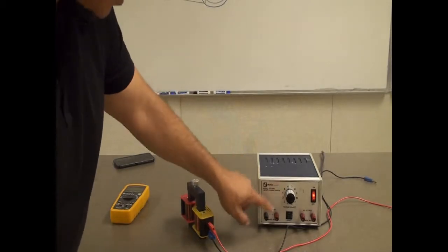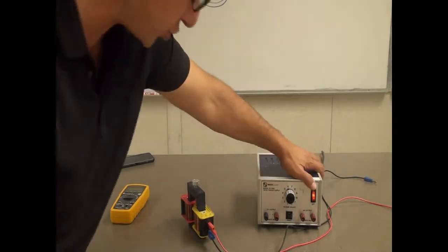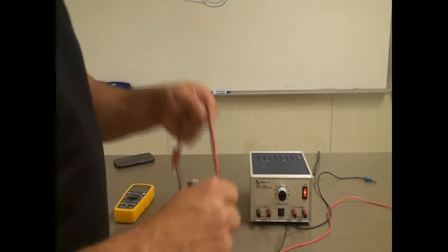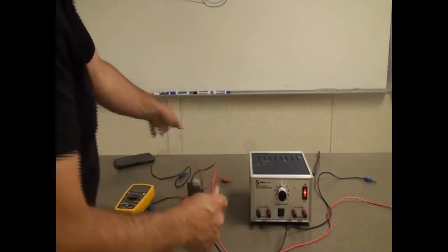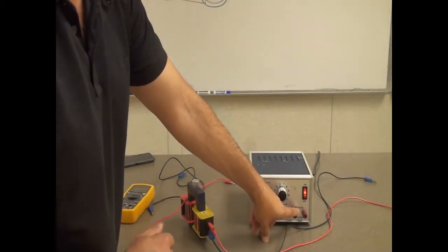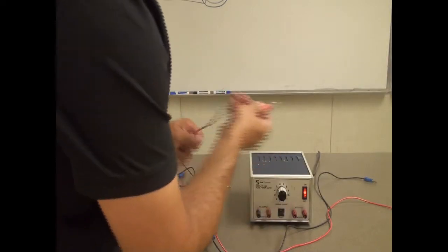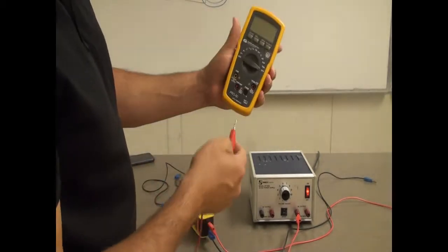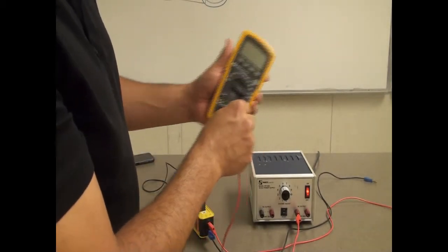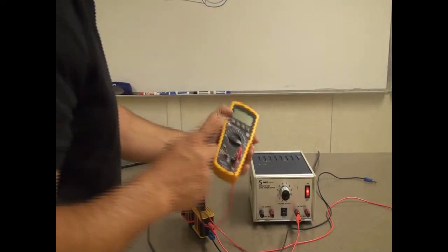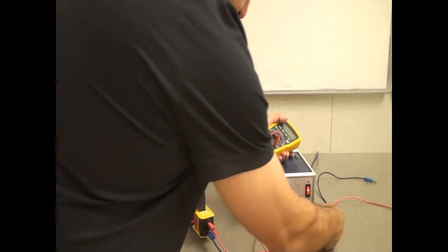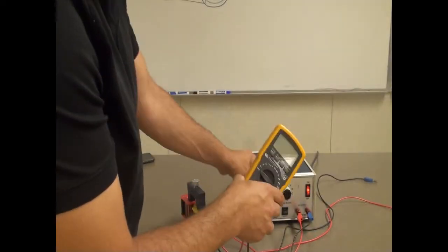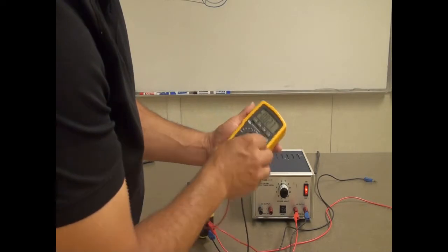So now let me put my power source on 6 volts. Then I'm going to measure the incoming voltage. So this one is DC, this one is AC. In order for the transformer to work, it has to be in AC mode. Okay, so I'm going to put AC here. Okay, then I'm going to put this on my voltmeter. Okay, so I'm just going to put this on volts. Okay, then I'm going to put this here, also on the common outlet. Then I'm going to measure the voltage here, put it on AC.